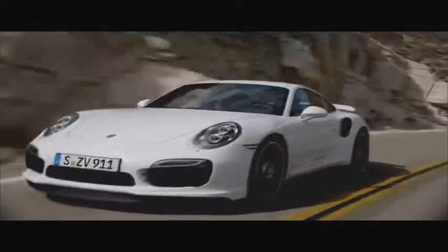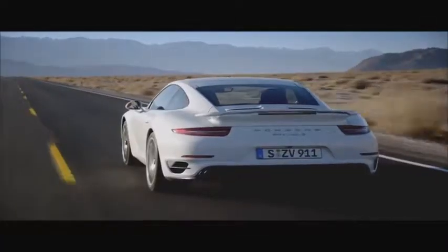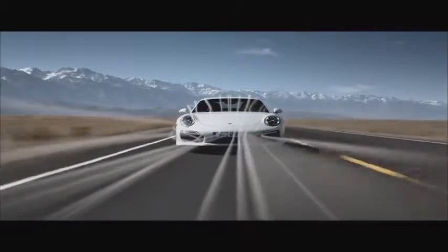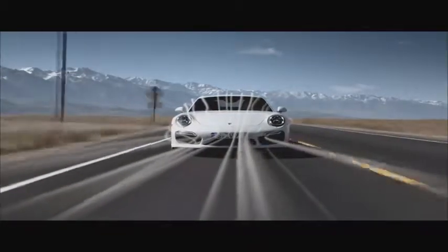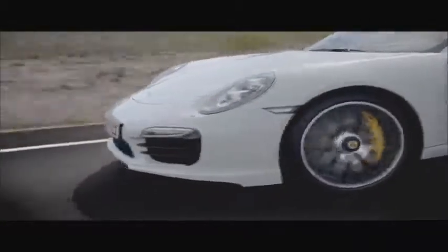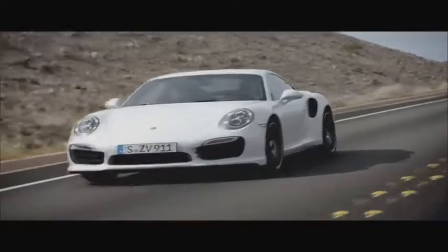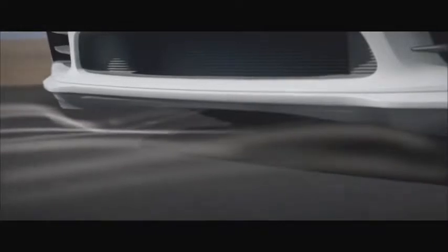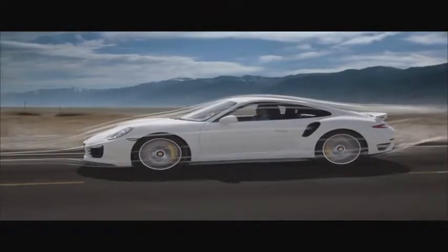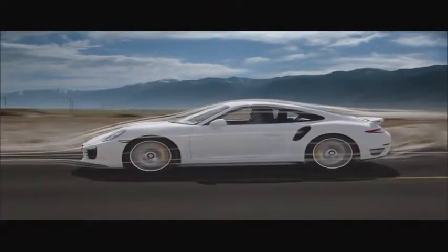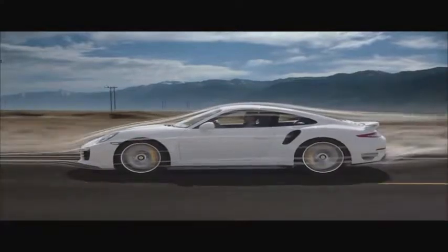The active front spoiler lip and the rear wing can be retracted and extended in 3 stages. Stage 1, start. Both spoilers are completely retracted. The greater road clearance at the front improves suitability for everyday driving. Stage 2, speed. From 120 kilometers per hour, the front spoiler and rear wing are partially extended. Agility and driving stability increase. Fuel consumption remains low, and the maximum top speed can be reached.